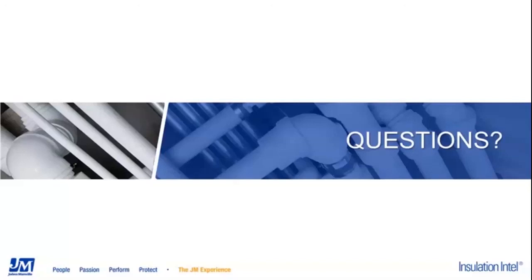All right, thank you, Natalia. John, the next question is for you: does the K value vary on service temperature? Yes, it does. The thermal conductivity will increase with increasing temperatures, and this is shown on a number of our product data sheets for the mechanical insulation products. All right, thank you, John.